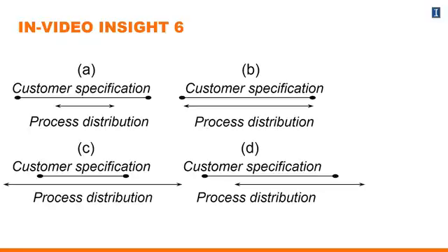In other words, what you can generally say is that the CPK value is always going to be either equal to or less than the CP value. Right? So if you've already calculated a CP value that's less than 1, the CPK value is either going to be equal to that or less than that, so there's no point of even looking at the CPK value.